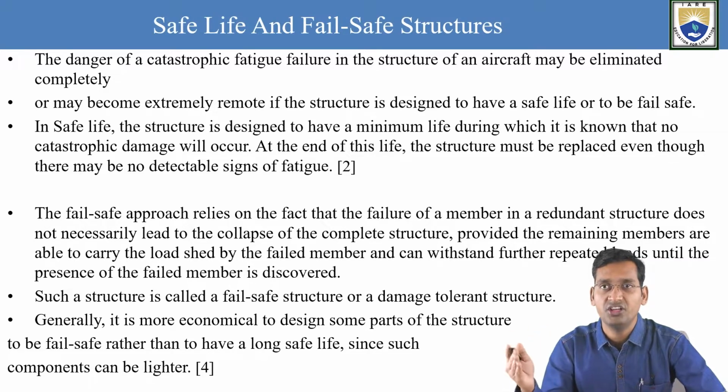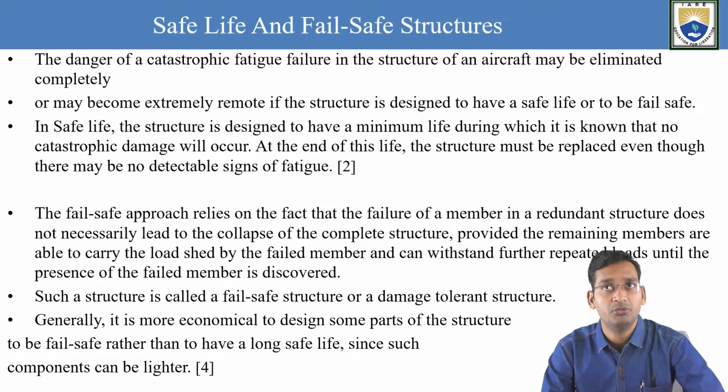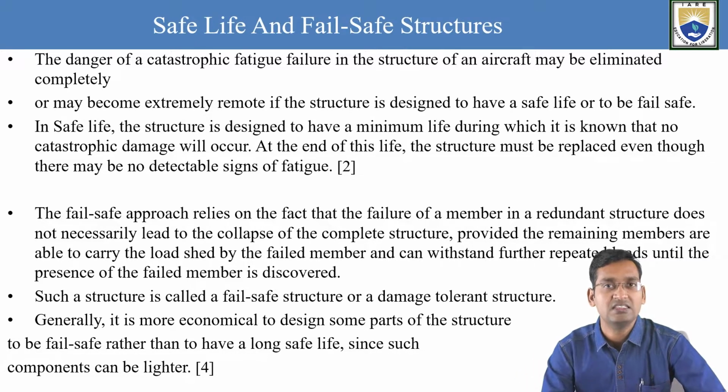Before reaching its end, that means before the refill runs out, you change the pen itself, so no tension about the refill running out. Similarly here, damage will occur, so before that we have to change. At the end of this life, the structure must be replaced even though there may be no detectable sign of fatigue. Similarly, even though you can see the refill is half filled, you still replace it so that during the exam no problem will be there. That comes under safe life.